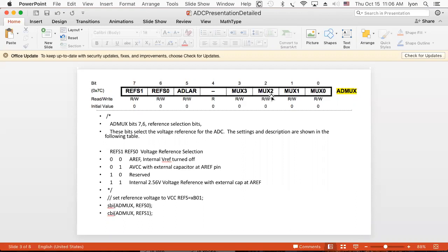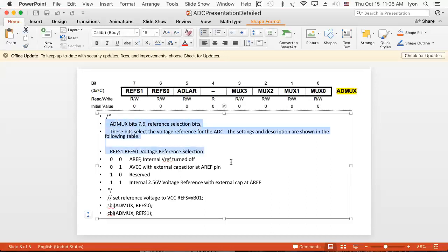And keep in mind, there's only one analog to digital converter here. We just have to analog multiplex the input lines and choose which one we want to use when we want to do our conversion, because we can only convert one line at a time, because we only got one ADC converter, and that's it. And then there's this thing here which I snarfed from the data sheet,